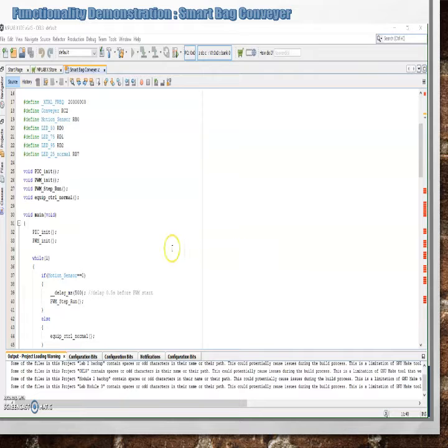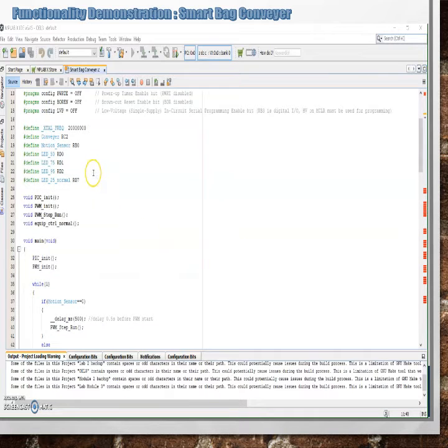First, we define our program: conveyor 2 at pin RC2, motion sensor at pin RB0, indicator lamp for 50% at pin RD0, 75% at pin RD1, 95% at RD2, and lastly 25% at normal condition, RD7. It will show the indicator for our conveyor motor speed.